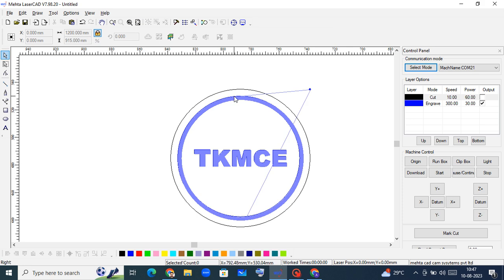see this, the engraving process started with this outer contour. Once it met the next closed contour, the engraving stopped over there, and it will go further inside. Again, when it sees another closed contour, it will do the engraving process inside. That's how the engraving process works. So this is what I'm going to create. Okay,